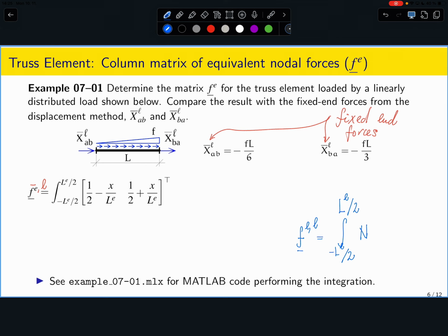Here I have the matrix of basis functions transposed times that given intensity of the distributed load effect. So this is what I had derived before. And this is something which I multiply with the virtual displacement. I will get the virtual work done by external forces. So what I have here is exactly this formula, which is now ready for being deployed.